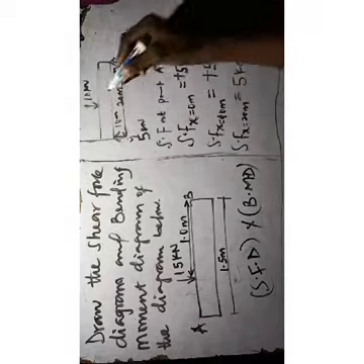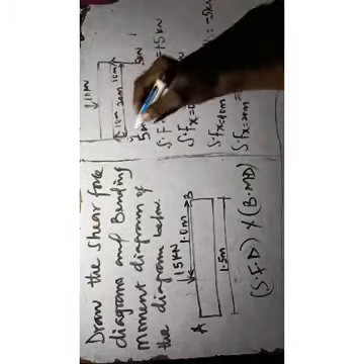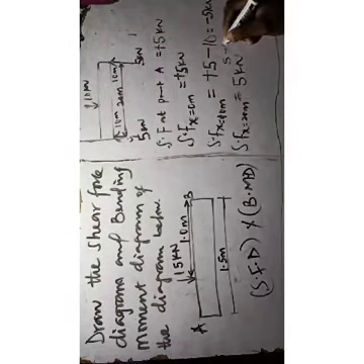Okay. So also it remains constant up to B, and the shear force at that end there is very constant. So the shear force is equivalent to 5 kilonewton. But if you resolve it, that will give you 10. It will always resolve back to 0. That will be minus 5 from here, the shear force at this point. So you can also say it to be what? 5 minus 10 plus 5. That will be equal to 0, and the shear force will go back to 0. Or you can simply say plus 5. It will still come back to 0. Okay, that is for shear force.